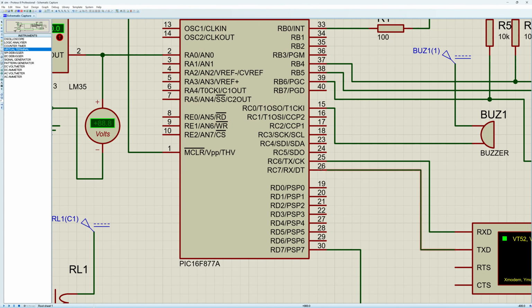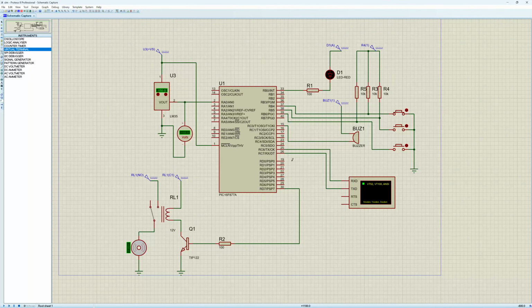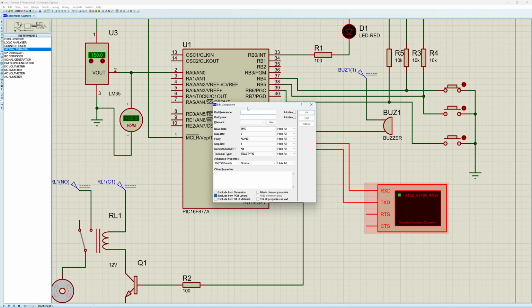These are the two pins we are going to use when we use a GSM modem, GPS, or any other serial peripheral. We can use these two pins to communicate with that peripheral. Here we need to configure its baud rate. I wanted 9600 baud rate only.